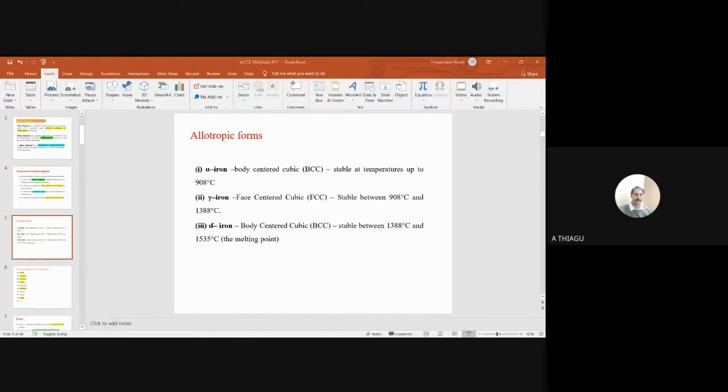So steel is 0 to 2% carbon, and 2 to 4.7% of carbon we call cast iron. Again, we have three types of steel material: eutectoid steel, hypo-eutectoid steel, hyper-eutectoid steel. Hypo means less than 0.7 percentage, hyper means 0.7 to 2 percentage. Okay, so these are the particular contents which we have obtained with the help of the iron carbon diagram, or sometimes we can say the phase diagram. Okay, so I will move to the next one. I hope you can understand the thing.